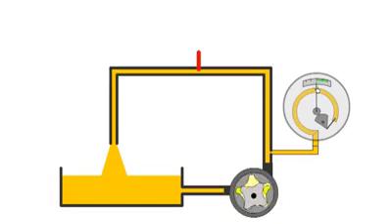If we close the valve further, we see another increase in pressure. We cannot close the valve fully because this is a positive displacement pump. If the valve is fully closed, pressure will rise sharply and something will break. Usually a pressure relief valve is used to protect against this situation. When the valve is opened, there is no restriction and we lose oil pressure.